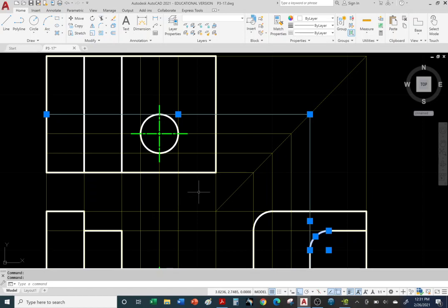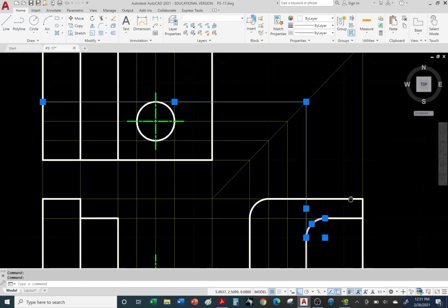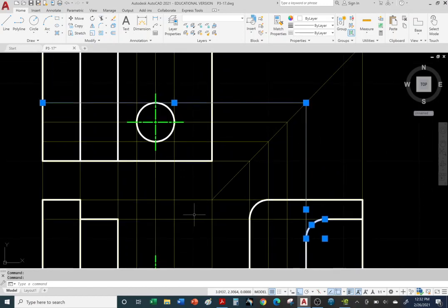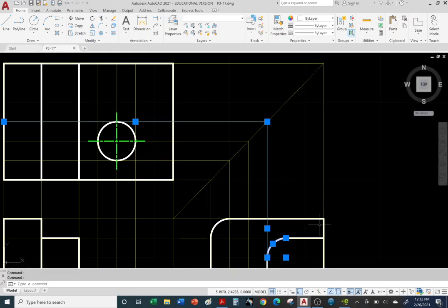Okay, and just a reminder, how did I come up with that 45? Well, when you start doing your own construction lines, you start by drawing a rectangular box around each view before you start drawing. It's just easier when you draw a box. Then you draw a box for this one, right? Then from the corner of the front view box, okay, so this is the front view box. From this corner, you draw a 45. And then from the right side view, you go straight up, hit the 45, go across to then create this box, right? So from the right side view, once again, you go straight up, hit the 45 and across. So that guarantees everything is lining up.